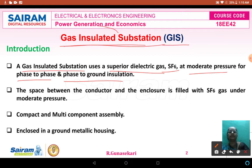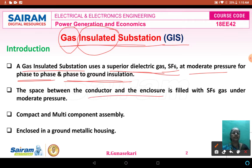The name itself says insulated. What insulation? Phase to phase insulation and phase to ground insulation. Which one is used? Gas. Gas means a superior dielectric gas. SF6 only is used as the gas for phase to phase or phase to ground insulation. The space between the conductor and the enclosure is filled with SF6 gas under moderate pressure.